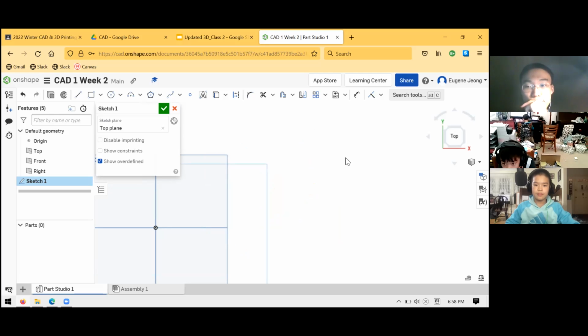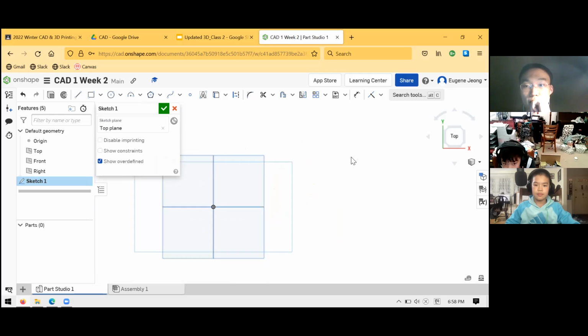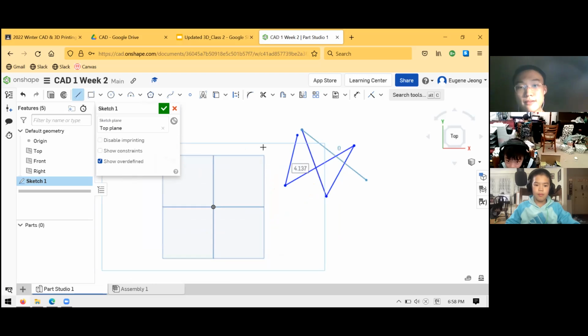When I also do the right click, it does not work. And when I'm done with the line, it keeps showing the line, and I cannot delete. Okay. Yeah. What's happening there is, like I said, when you're done using a tool, you need to tell Onshape that you're done using the tool, or it won't let you do things. Like in your case, you found out that it won't let you delete if you're still using the sketch tool, or the line tool. So what's happening there, you're seeing something like this.